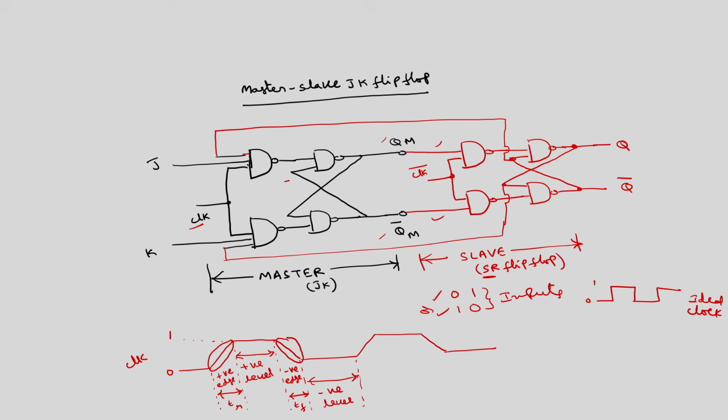Now from here to here is a total of 1 clock cycle, and from here to here is 1 clock cycle. What is required here in this JK flip flop is that over this entire 1 clock cycle I have to change the output by only 1 when J is equal to K is equal to 1. If I start from this point, then up to here will be 1 clock cycle. I will consider this clock cycle from here to here. This is also 1 clock cycle. You start with one point, you have to end with the same point. This is also another clock cycle.